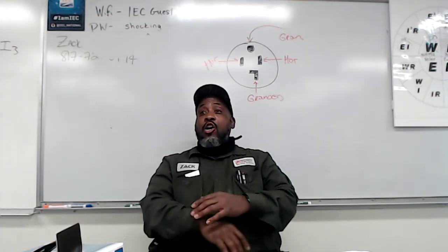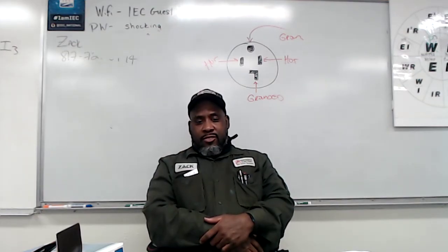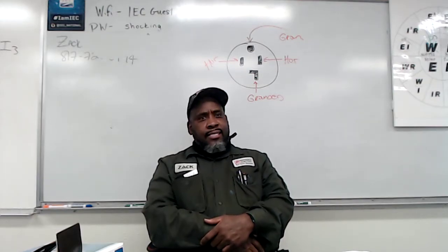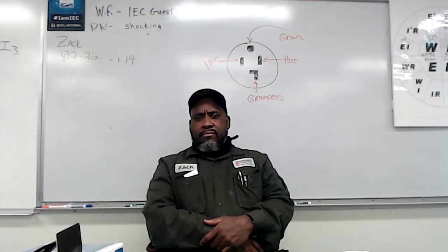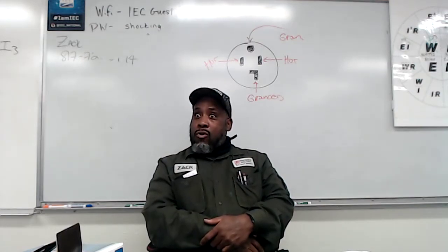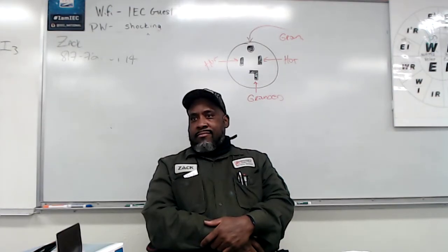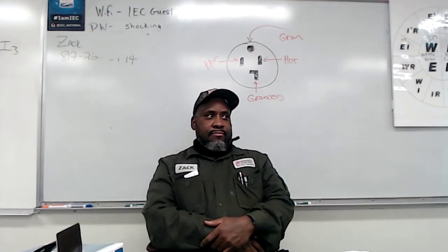So what do I know? What do I write down I have? 20 heads at 75 watts. That tells me something, don't it? And then I need to figure out what dimmer is going to hold that wattage. Questions. That's not hard.